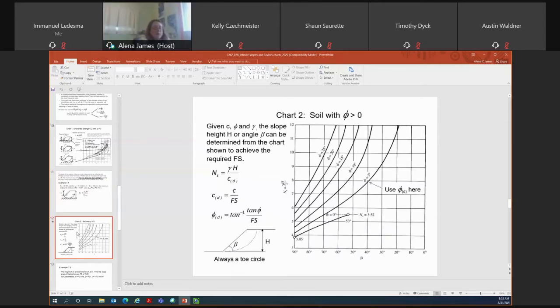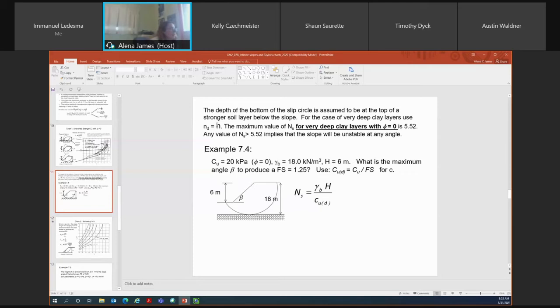Okay, there is another Taylor's chart. Oh, what's the little h? It's really the big H, Fabian. So ND is equal to big H. Right, what was phi again? In the case of undrained shear strength, phi is equal to 0. So phi is your friction angle.